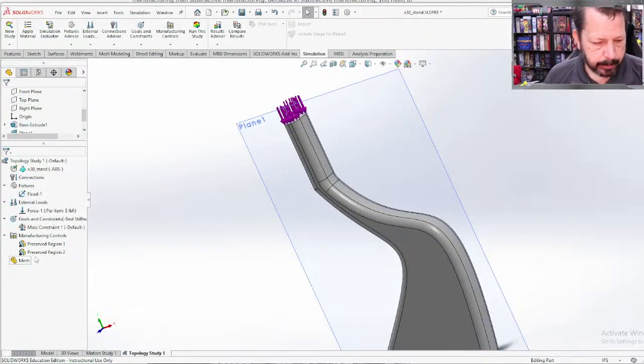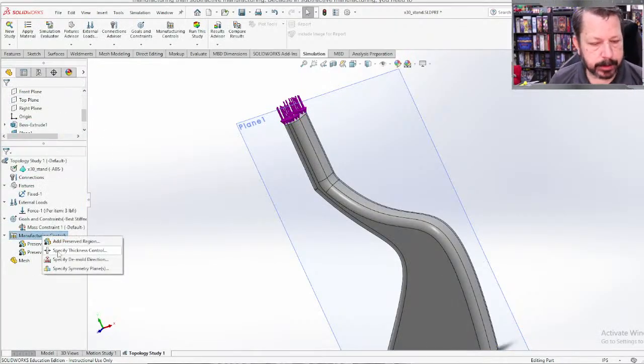Okay. And then I've also got in here thickness control, maybe part of what you're doing, the process itself, you can't have something that's thinner than a certain size. Maybe you're doing a casting, and if it gets too thin, it can't really cast very well. Or maybe even some of the metal additive manufacturing processes, if you try to print too thin, even though the geometry says to print it, it won't print very well. So there might be a minimum thickness that you have to maintain. I don't really have that here. I guess there is some, but this is really more for flat pieces.